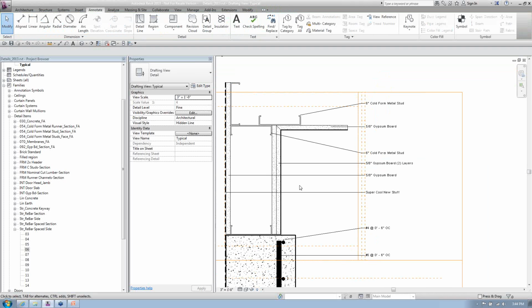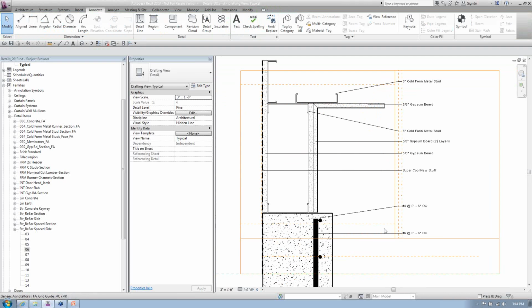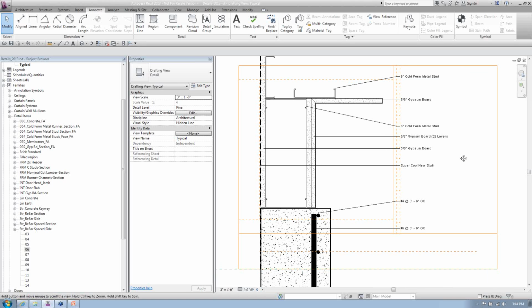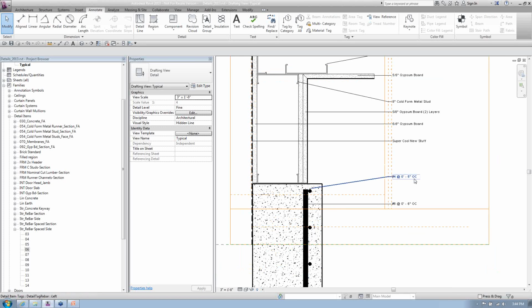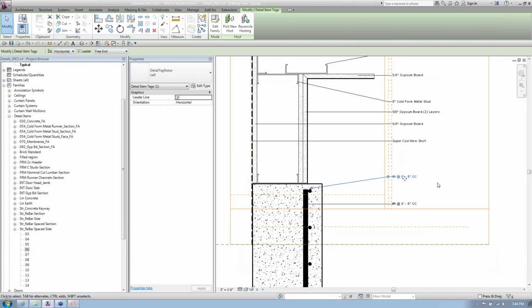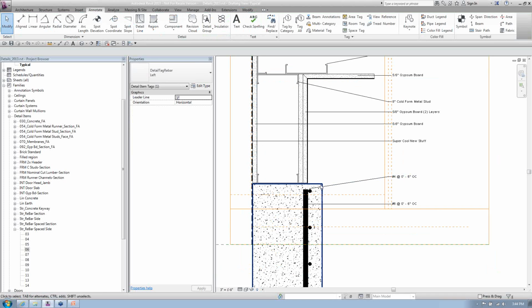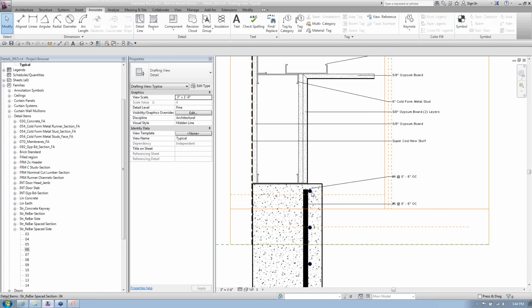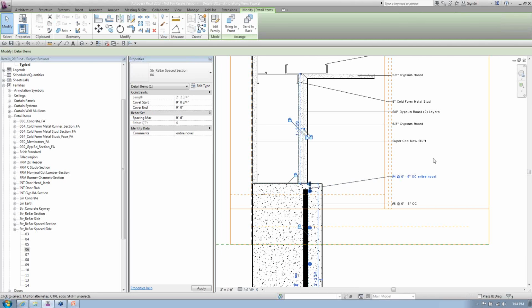Now, I'm not saying I never use text inside of here. If I've got to put a whole assembly description or an installation description or some sort of thing like that, absolutely I'm going to get into it. I know a lot of structural engineers don't just say number 4, 6 inches on center. They add an entire novel after that. Well, if that's the case, you can still do that. I can come down here and add an entire novel after this, and it'll still display.